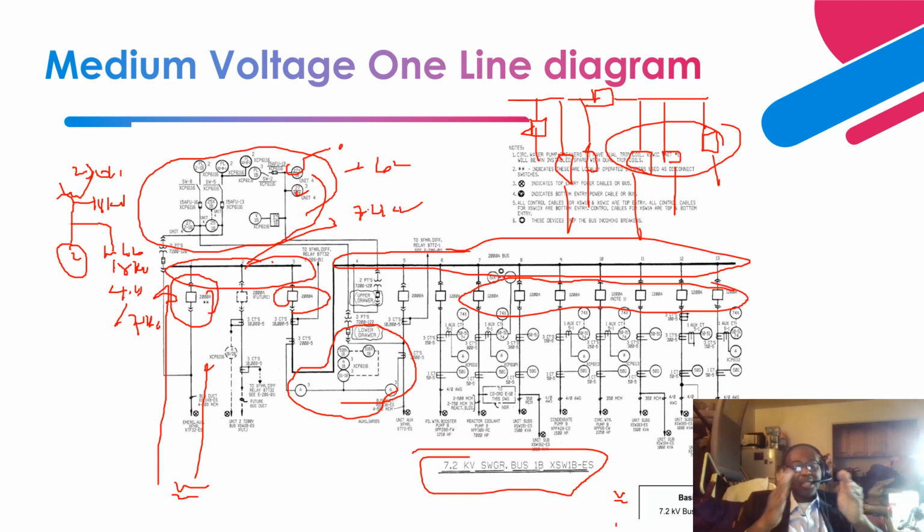Remember, I told you that, based on reliability, the goal to achieve redundancy, you have independent power feeds onto these buses. That is, the power feed to these buses is from a different source compared to the incomer feed that is coming over here.